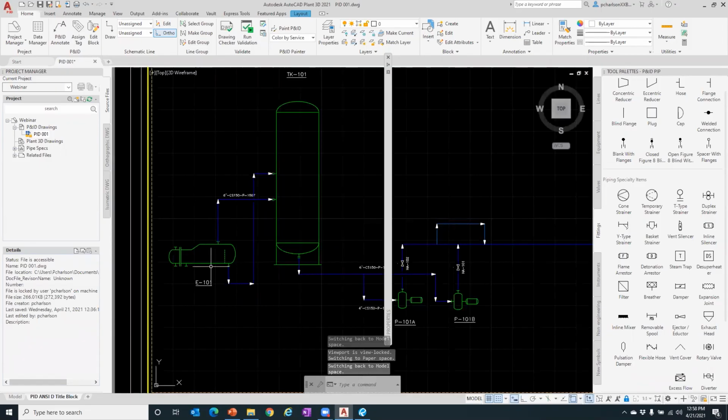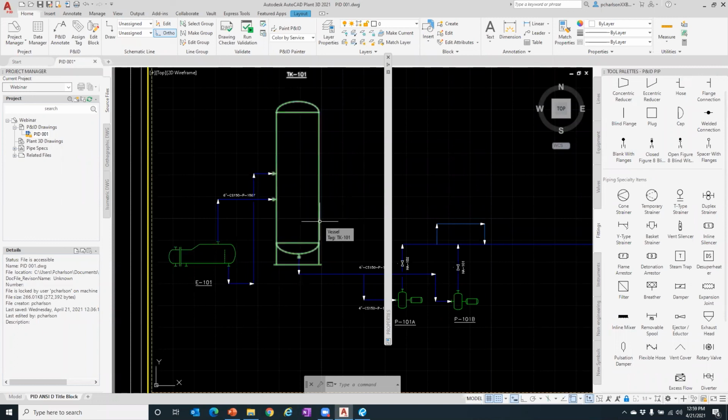But I think you can kind of see that if you have some of this set up, P&IDs can actually be pretty useful and a lot easier to work with than just AutoCAD type information. Again, you can't really add the line data into AutoCAD line work like you can within P&ID line work. So again, adding information into the components that we have here. Also, we can go in and create custom components pretty easily within here as well.